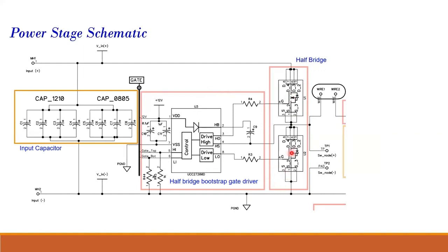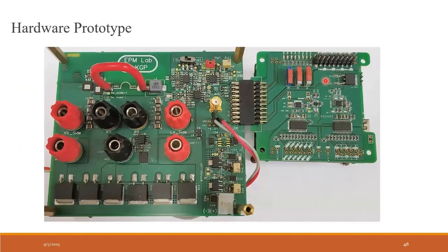This is the high side switch, there's the low side switch, and then from this switch node point there are these terminals, which are open. So for that we have this wire. Why do we have this wire? Because we connect a current probe across this, so that we can see the actual current flowing through the converter in the oscilloscope. Those current probes are very, very costly.